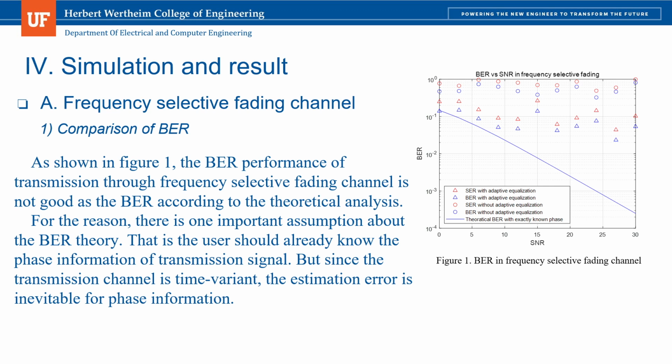For the reason, there is one important assumption about the BER theory. That is, the user should already know the phase information of the transmission signal. But since the transmission channel is time variant, the estimation error is inevitable for phase information.